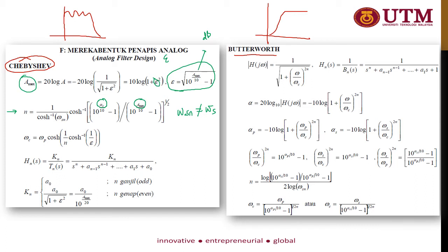all in dB. If for example Mx is given as 1 dB, you just put in 1 in here. You don't have to convert these dB values into linear. Same goes for alpha S. If alpha S is, for example, minus 30 dB, you just put in 30 in here. You don't have to consider the negative, and you also don't have to convert into linear values. So please make sure you put all parameters in dB values.